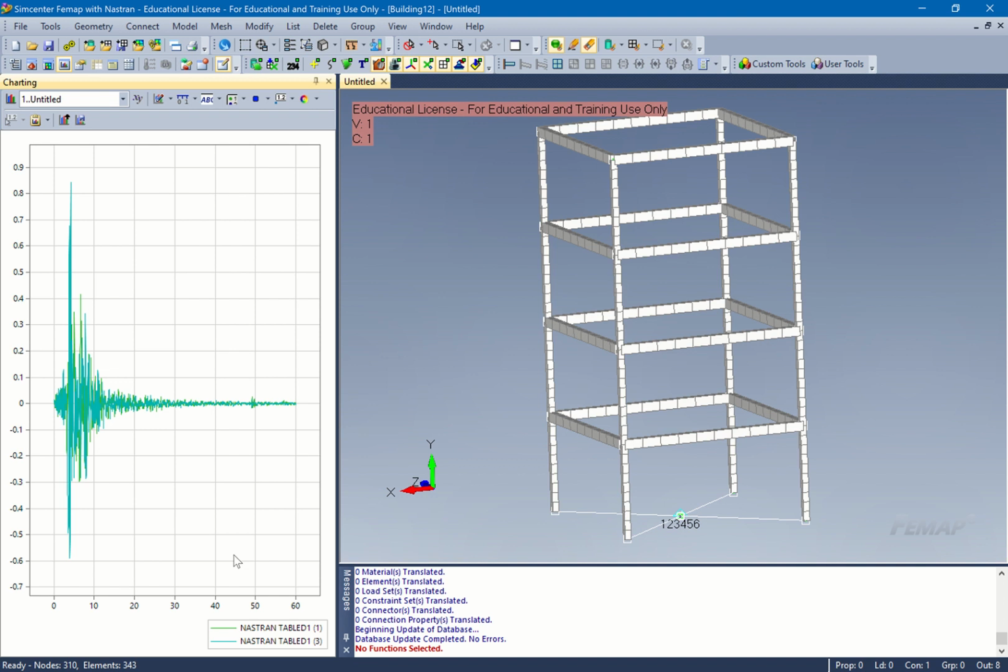Now what we're going to do is apply all 3 of them, X, Y, and Z, to the location below the springs, which would be the soil movement. Does that make sense? Yes, sir. How does Nastran know that this is acceleration? It doesn't. It has no idea it's acceleration. It's just raw data. I brought it in. Now we have to tell it what it is.